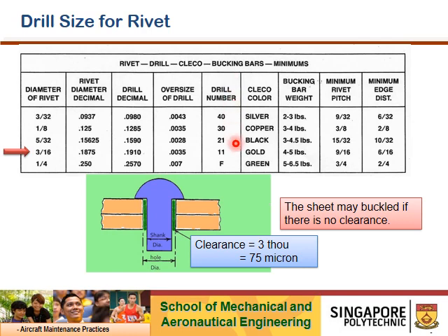Everybody will mention drill bit 11. So when we talk about drill bit 11, the common consensus is that it is a drill bit that gives me a hole diameter of 0.191 inch. So this is the common practice. If, let's say, I want to install a 1/8 inch diameter rivet, then of course I go to the tool store and tell the gentleman to give me a drill bit number 30. So on and so forth.